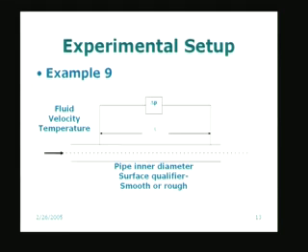That is something which we will talk about later. Temperature may be specified, either it may be a cold experiment or room temperature experiment where the temperature is not going to change, or the temperature may be held at a higher value by heating the fluid, in which case it is a high temperature experiment. But in general, when we are measuring the friction factor, we would like to have isothermal flow conditions. That means that the flow is at one single temperature.